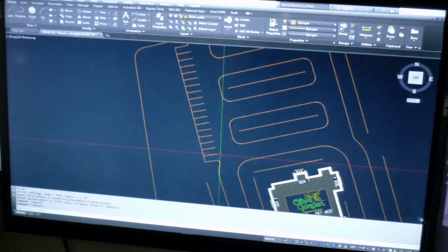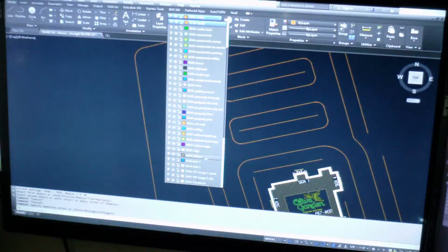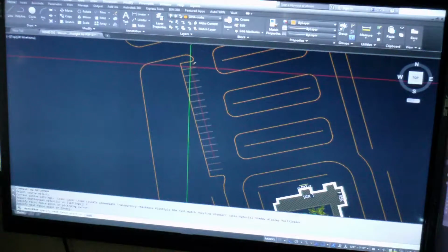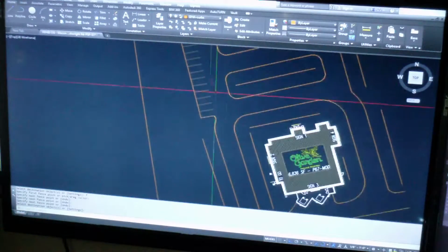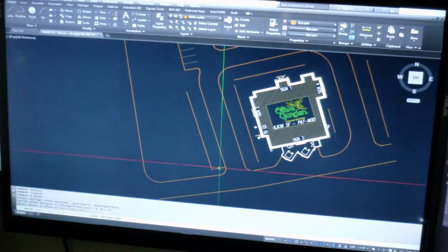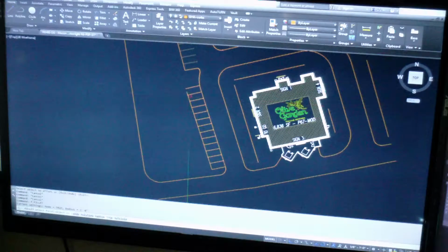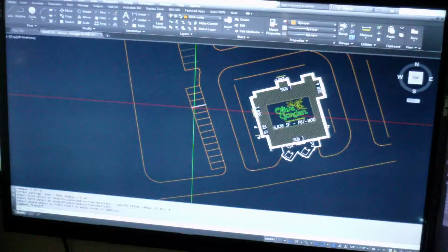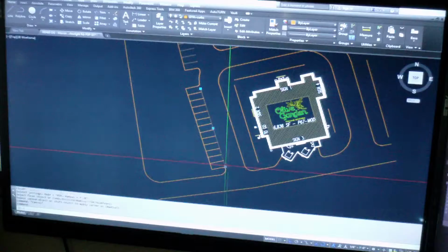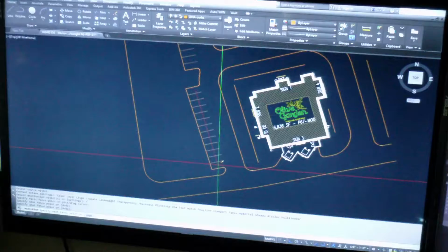And then these, I have a separate layer that I like to put these on for stripes. So I'm going to match and use a fence to get all those in there. So there's a row. So we come down here, I'm going to start from this end. I'll set 9 feet, multiple. I'll get one more in there. Fillet that at 0. Fillet radius 36. Base that, match, use a fence.